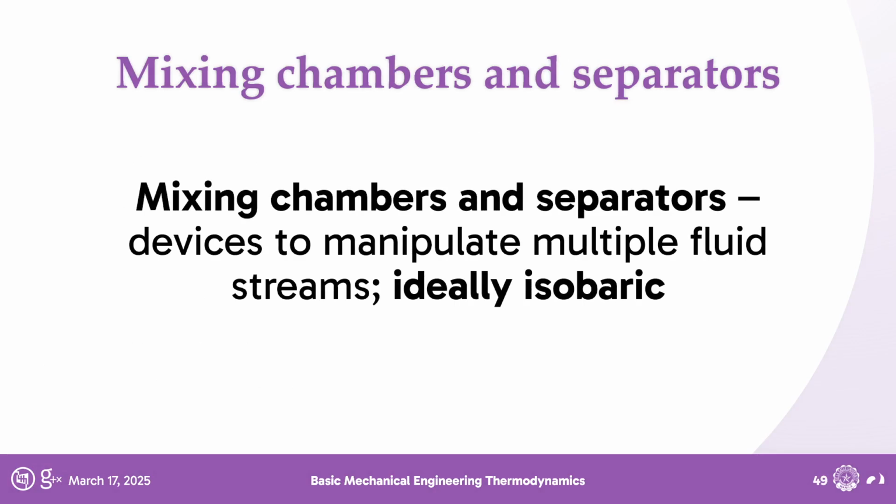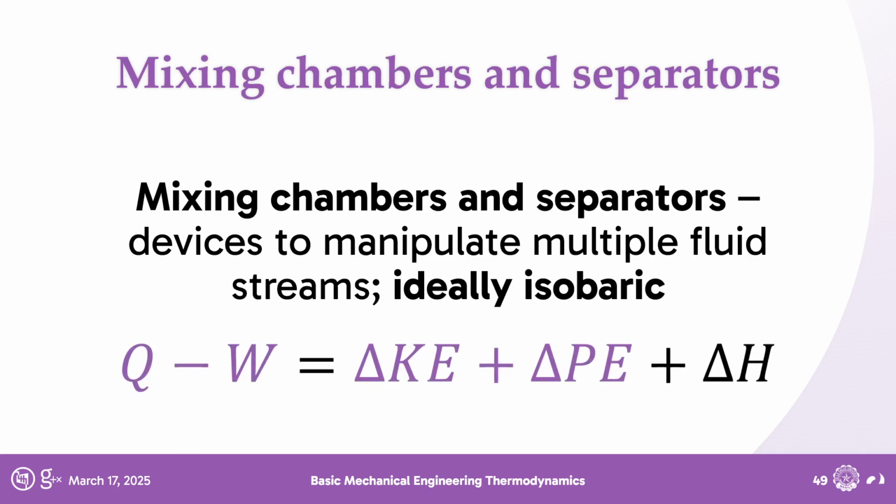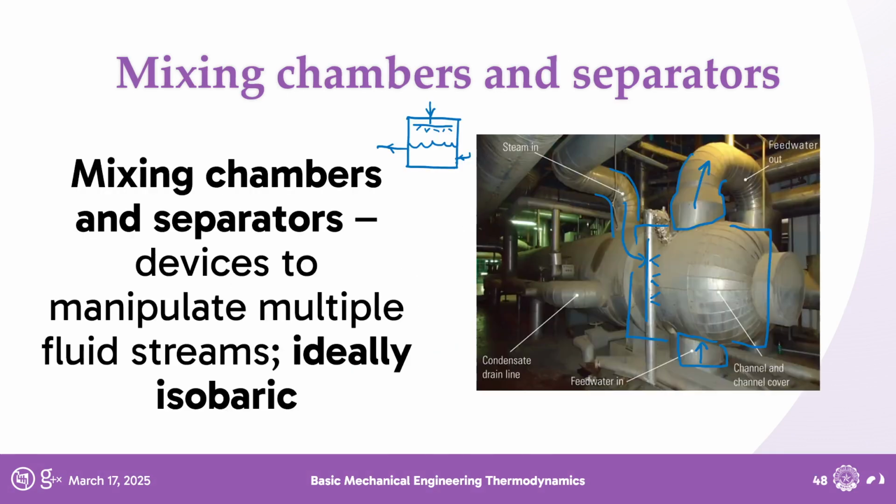And in this case, if you guys remember, for a mixing chamber to work, the pressure should ideally be the same, constant. And there you go again, there's no heat that should leak out of the mixing chamber, and the mixing chamber usually has no moving parts, so there's no work, right? There's no KE and PE as well because they're insignificant. So again, your incoming enthalpy should be the same as your outgoing enthalpy.